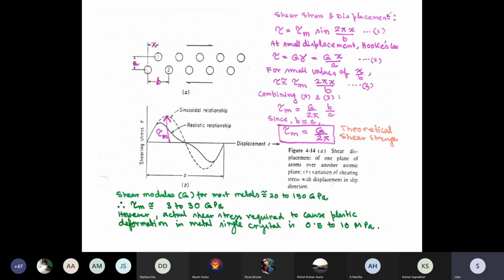And you learn in this chapter that the movement of dislocation gives ductility to the material. So if you hinder the movement of dislocation in a material, you can increase its strength, and this fine precipitate hinders the motion of the dislocation. Thus it increases the strength of the material. So this will be taught gradually starting from this semester. So for the time being, you form by certain thermal treatment a second thermodynamic phase, which is very small in volume, in a matrix of the parent phase, which improves certain mechanical properties like strength.